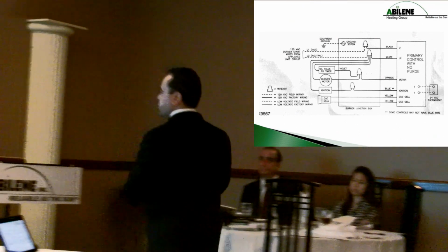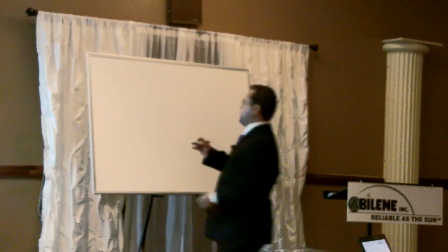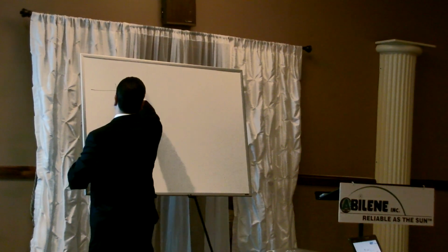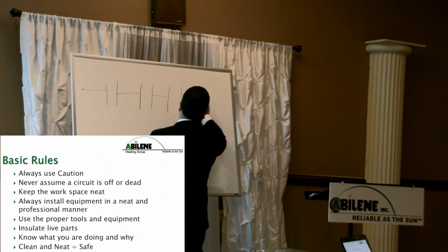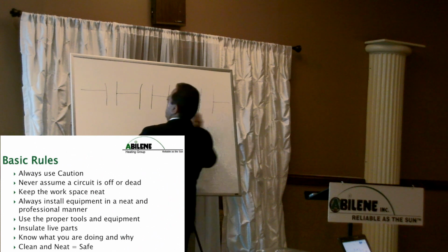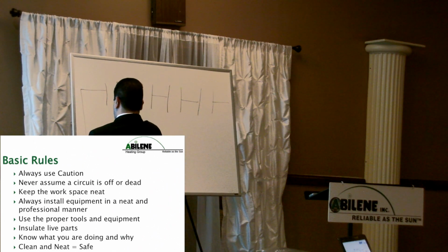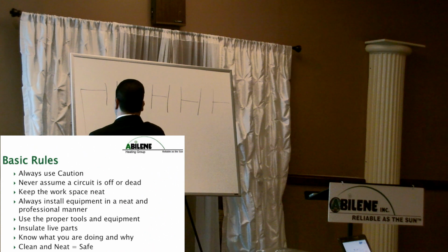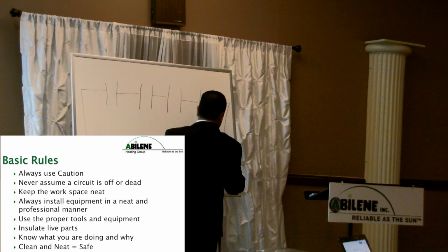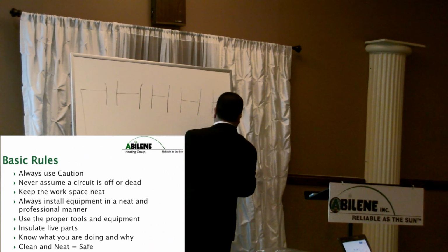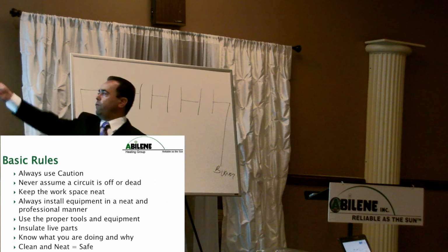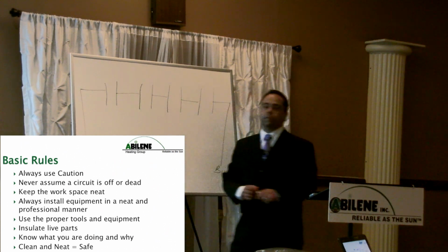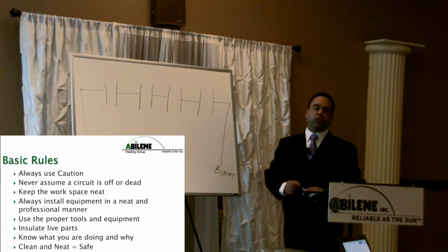So what turns it on and off? Switches. Very good. Our electricians know this. So 110 volts is going to fire that burner, as long as all the switches are made.